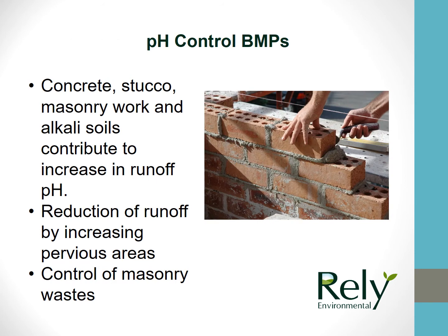Controlling pH from leaving a property is important. Concrete, stucco, masonry work, and alkali soils contribute to increase in pH runoff. Reduction of runoff is possible by increasing pervious areas. Be sure to control produced masonry waste.